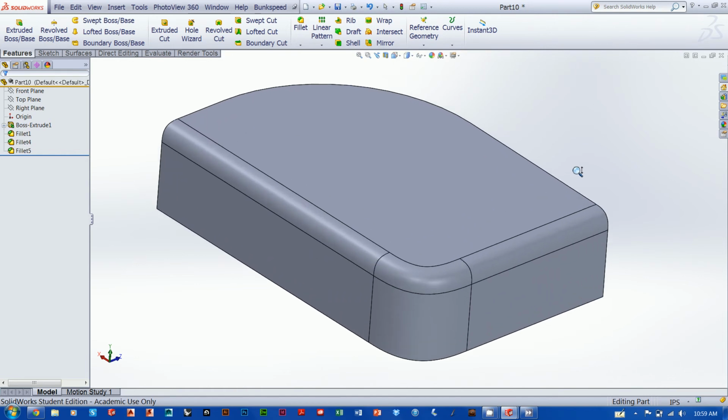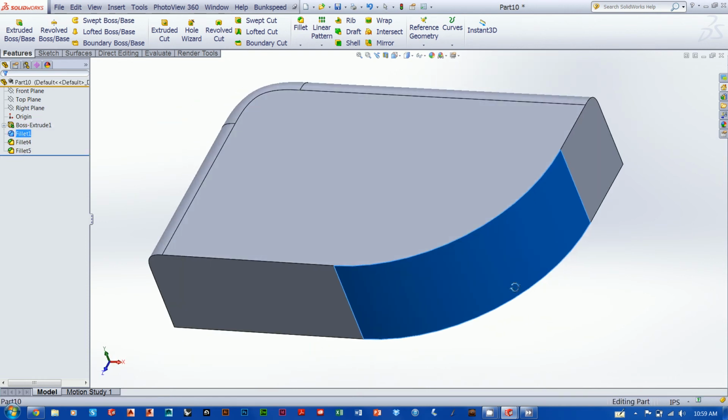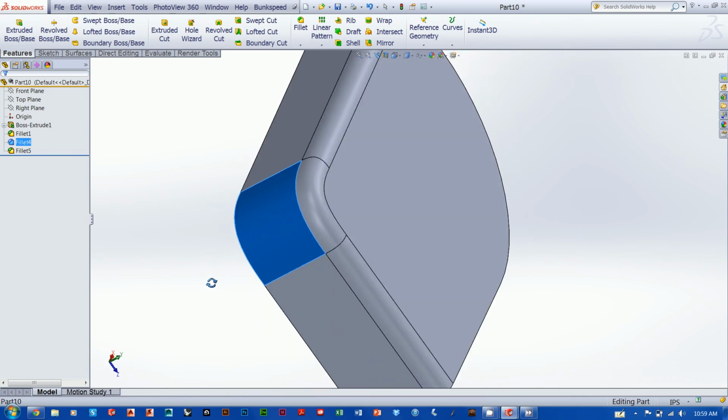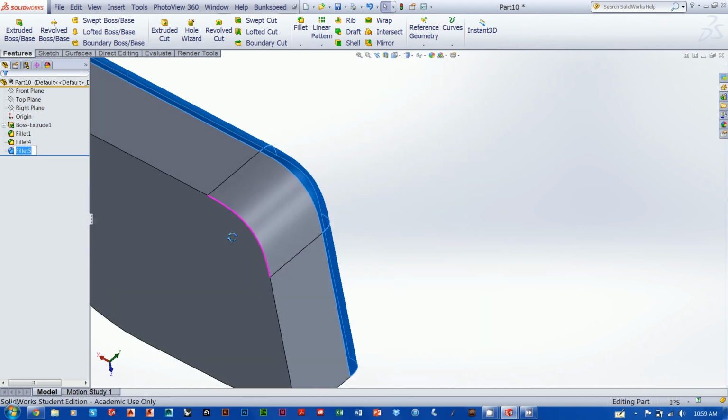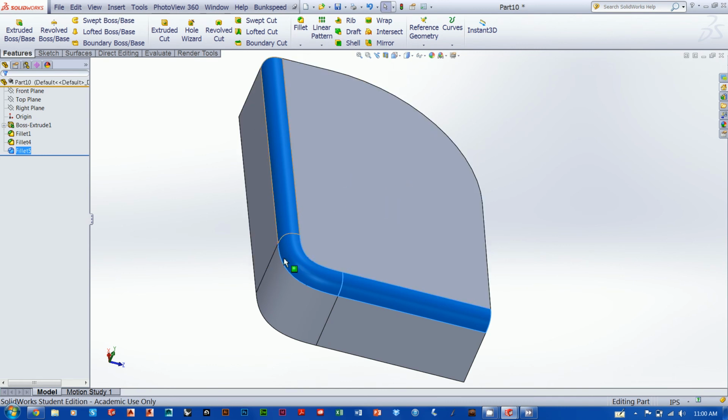to your parts, and fillets are really fun to use, and we're going to be using them all over the place. Don't forget that everything is adjustable, everything is flexible in SolidWorks, so we've got all three instances of each fillet. Each job that we did there is totally editable. We've got our first fillet, which is up here at the top, fillet 1, which was our full round fillet. We can go back in there and edit that. We've got fillet 4 turns out to be the face fillet that we added on this side, and fillet 5 is right there where we created a face fillet between this top face and these three edges.